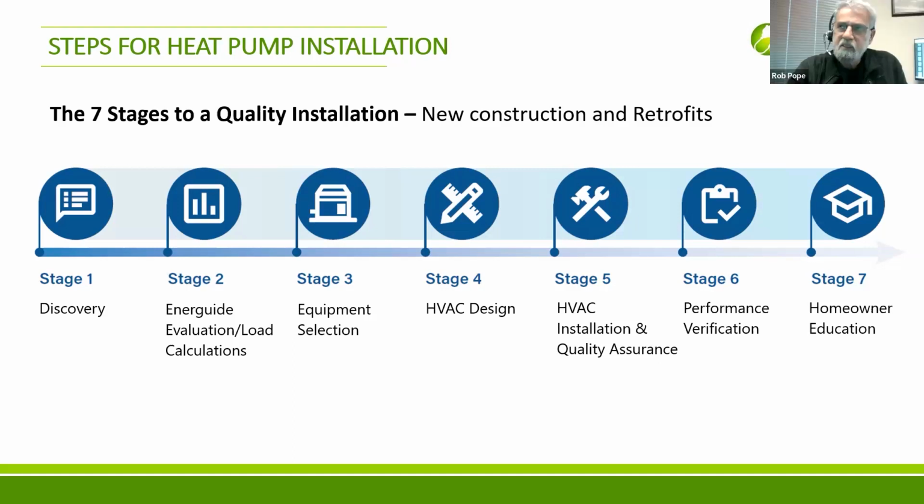Well, yeah. So here's the calculation that I always make. If it's a new home, especially, you need to manage air quality, so you need an HRV system in there anyway. So you've got to put ducting around. You also want to filter the air well if you can. So you want a MERV 8.